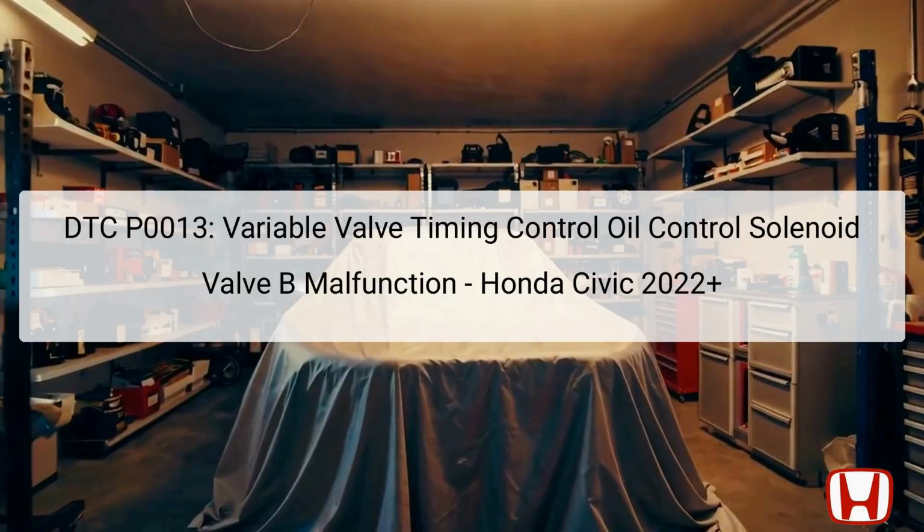The DTC P0013 refers to a malfunction in the variable valve timing control (VTC) oil control solenoid valve B within the Honda Civic models from 2022 onwards. The VTC system plays a critical role in enhancing engine performance by allowing for variable valve timing, thus optimizing power and fuel efficiency.